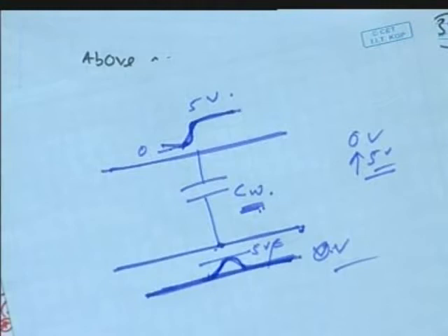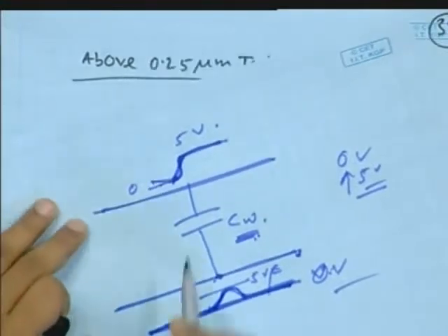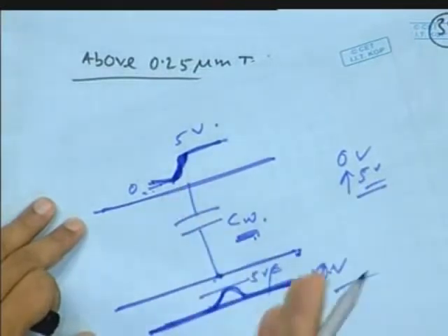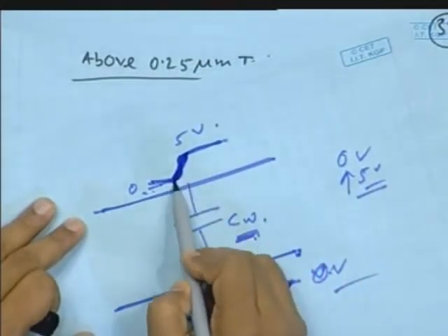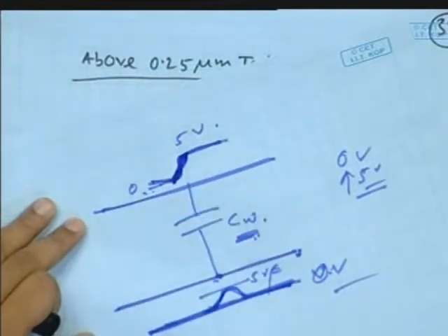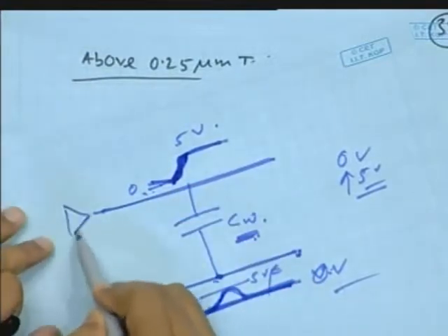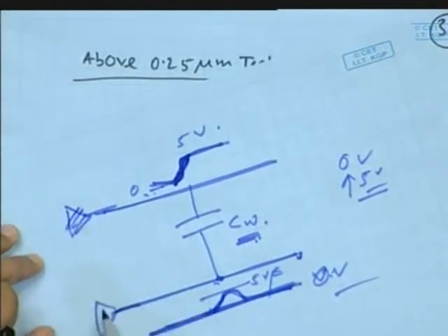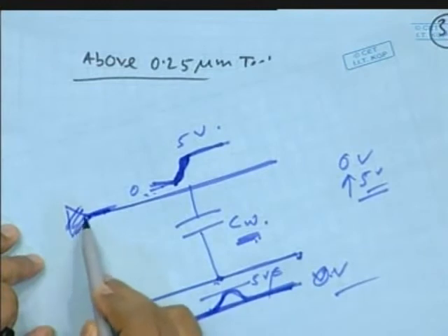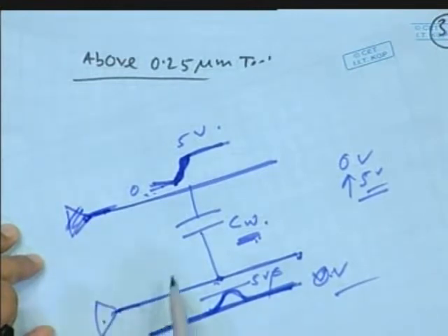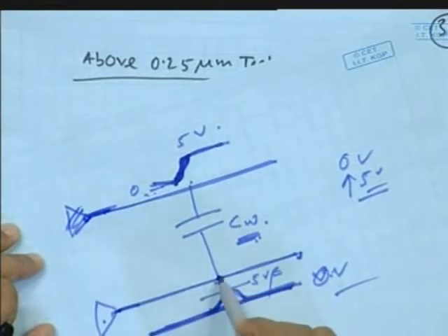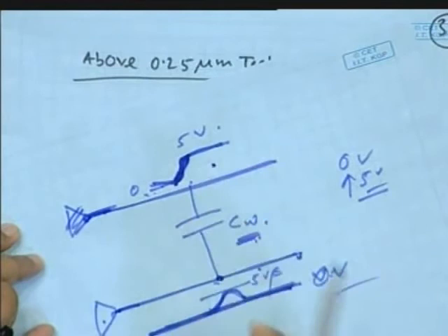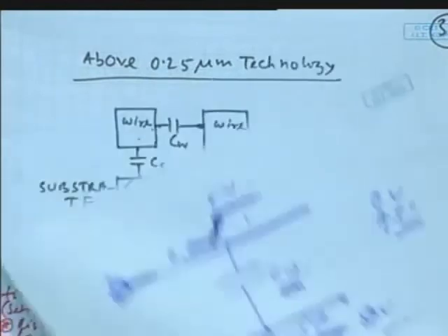So if the driving strength of this one, meaning the slew, this tan theta, is very steep, this one will try to dominate over the other. There is a driver, a buffer is the driver. If the current capability of this one is very strong compared to the other, it will dominate over it. The other will also have some effect on this one, but that can be negligible.